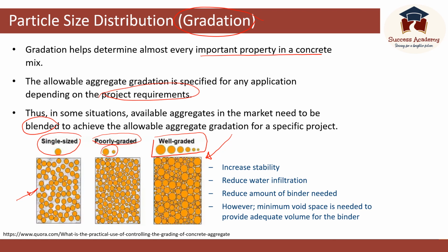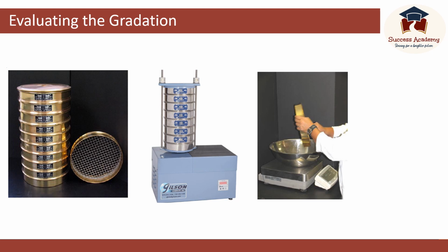There are some advantages of having well graded aggregates. It increases the stability, it reduces the water infiltration, and it reduces the amount of binder needed. However, minimum void space is needed to provide adequate volume for the binder, so well graded is not specified in every application. Let's see how to evaluate the particle size distribution of an aggregate lot.